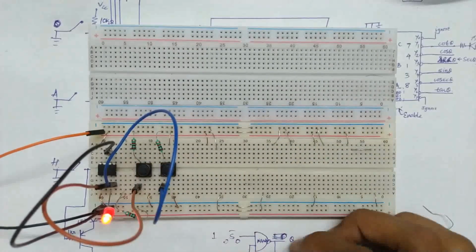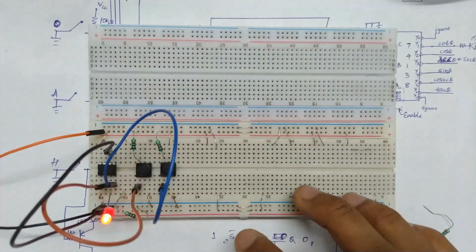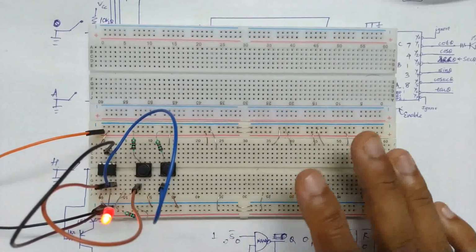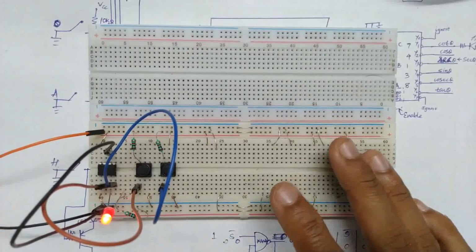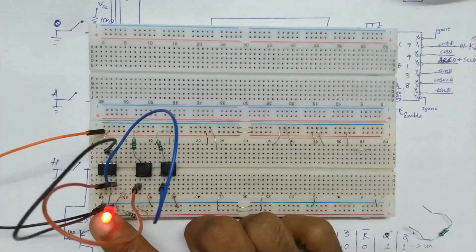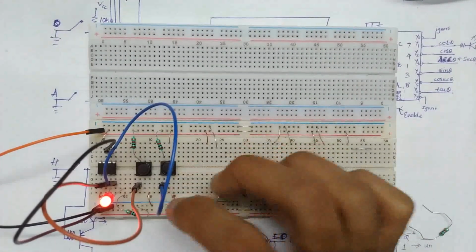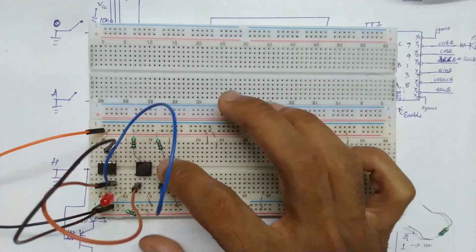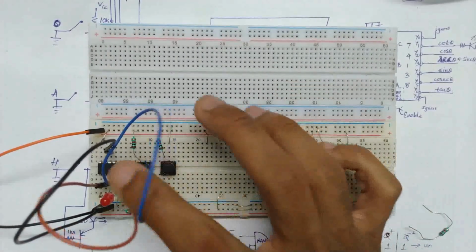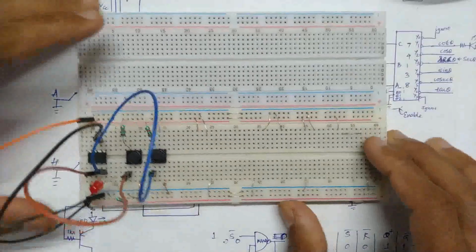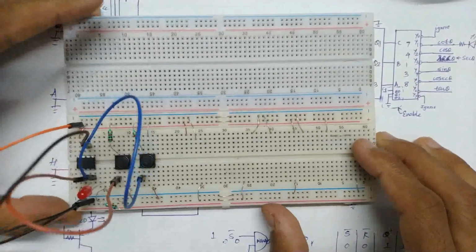So once I set it, it's set completely, in the sense I don't need to do any further action, and it'll just remain in this set state, or its output will always be 1 until I come back and press this reset button. So this is basically the S-bar R-bar latch. This is how you essentially use the S-bar R-bar latch of the 555 timer.